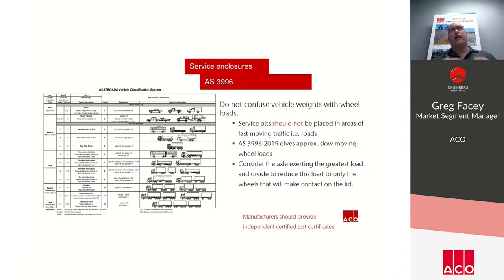So often, for example, it might be a 10-tonne truck with 4 wheels, but the cover doesn't need to withstand a load of 10 tonne. It's only the wheel that's traversing that particular cover system, so 2.5 tonne. So just consider the wheel load that's going to be applied to that system, because that considers 2 things. One, not over-designing and adding more cost in particular, but we also don't want to go the other way and under-design and then have a cover that may fail. So understanding the wheel load that's going to be exerted on the system is important.